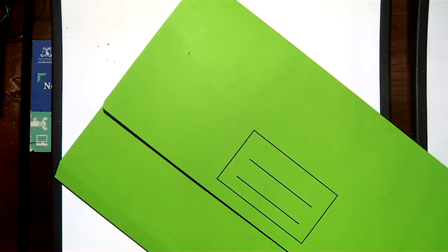So all I'm trying to do is give you a little bit of insight into, hey, if I'm really building this, and really when you go high speed electronics, you would never do this. You would only do this if you're building something slow, maybe high voltage. Right? But if you're doing this, you would always build it on a chip. And if you're building it on a chip, make sure you don't do something silly by adding 2 diffusion wells when you don't need to. That's what it is. Okay?